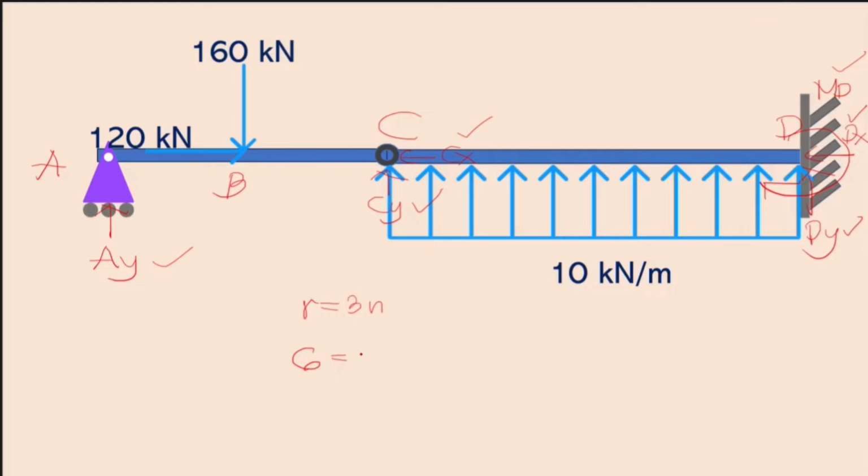And then that should be equal to 3 times the number of members, which is dalawa. Kasi again, this is our first member, and this is our second member. So we have 2 here. Now, itong left and right side should be equal for the beam to be determinate. And so, diba, this will reduce into 6 is equal to 3 times 2, which is 6. And so, our beam will be determinate. This is how you can check.